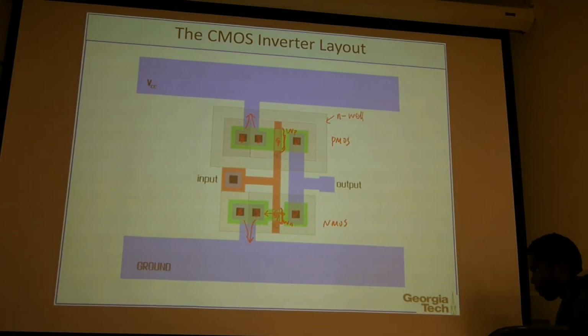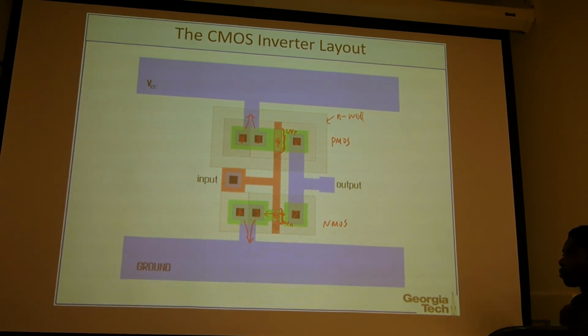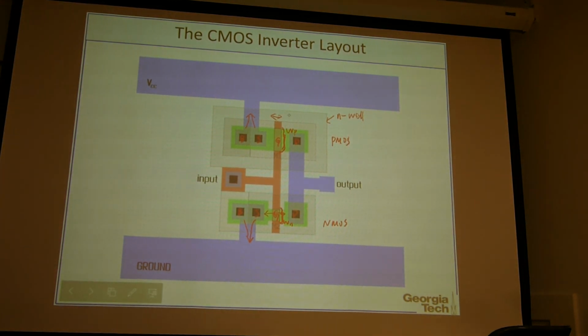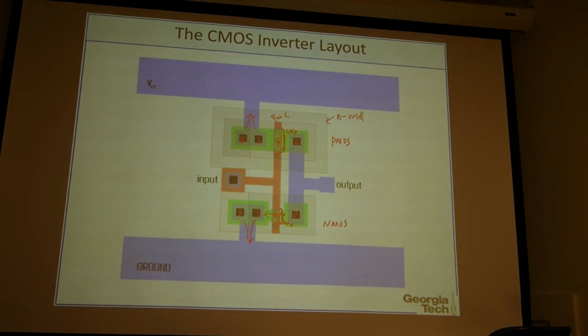So your job as a circuit designer is to determine those W. Because as a circuit designer, you cannot change the L. With the same topology, you have the same L. And you go through the same fabrication, so the oxide thickness is also the same for the NMOS and PMOS.